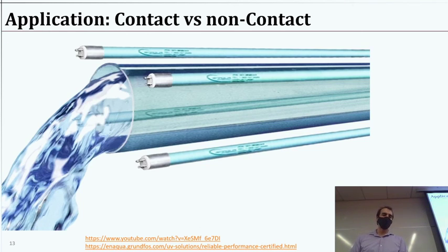What he's comparing it to is their new technology, where they were able to make plastic that had enough UV transmittance to make it worthwhile. I think he said it was an activated fluoropolymer of some sort. So it's kind of like PTFE or something, where it's fluorinated something, and I don't know the exact chemical makeup, but essentially what they're doing is having that plastic casing that the water is flowing through, and then having the lamps around the outside shining in through it.